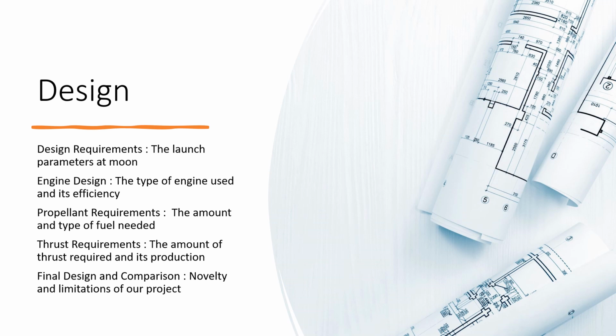After that, we discussed fuel and oxidizer properties. We decided on monomethylhydrazine and dinitrogen tetroxide. More on that in a minute. Next, we calculated the thrust required to take off the lunar surface. This ended up being about 14 kilonewtons. Finally, we discussed the limitations of our project. This mainly included research into the regulations surrounding the fuels we chose.